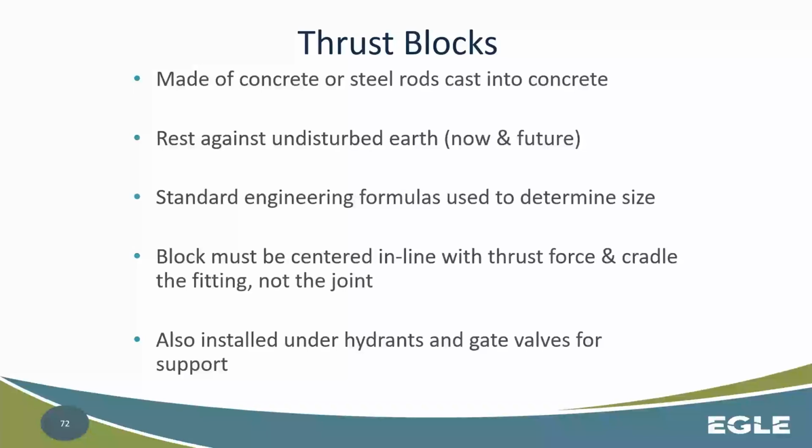Okay, that's a big one. So not the joints themselves, but the fitting itself. Make sure that fitting doesn't move. If the fitting doesn't move, then the joints won't move. We don't need to focus on the joints because there's more chance for error. We need to focus on the fitting itself. Make sure that fitting doesn't move. Okay. And also installed under hydrants and gate valves as some other fittings, things like that, rather than just elbows and Ys and things like that, crosses.